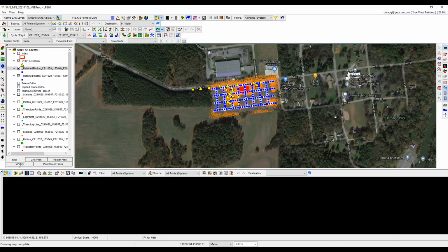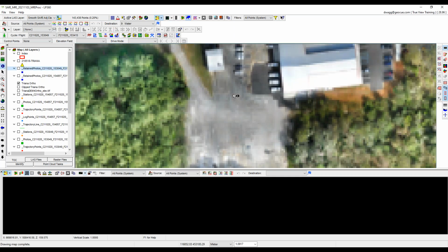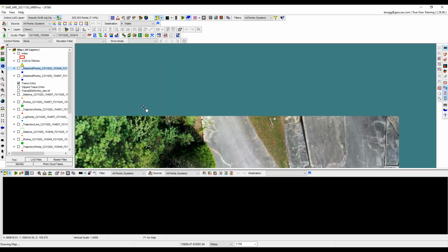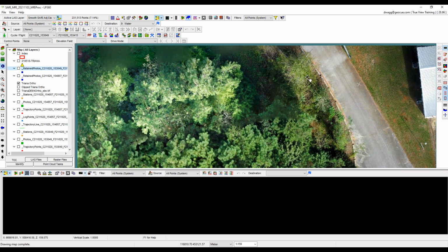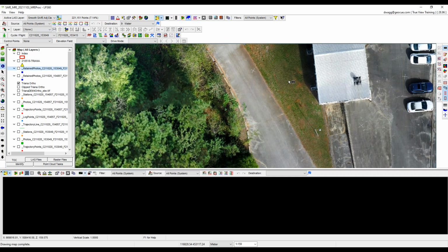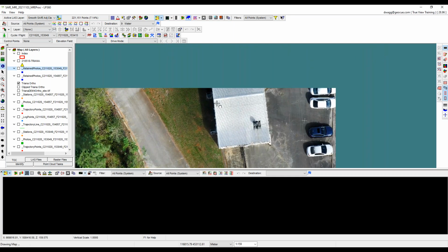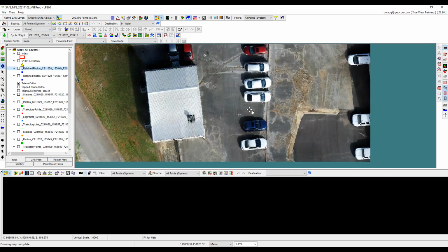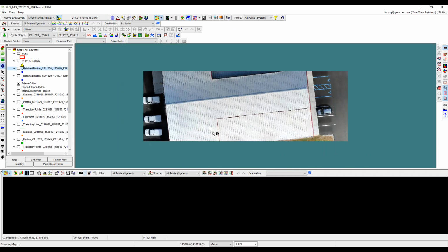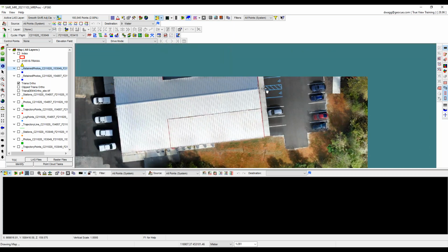So we kind of get two things out of this process: we get that updated image positions and orientations, plus you get the nice ortho, where we get some good quality in the vegetated areas off the northeast there. We have kind of our true ortho, where we've used the point cloud to give us the roof of the building.